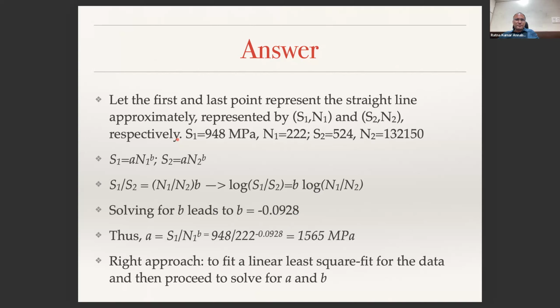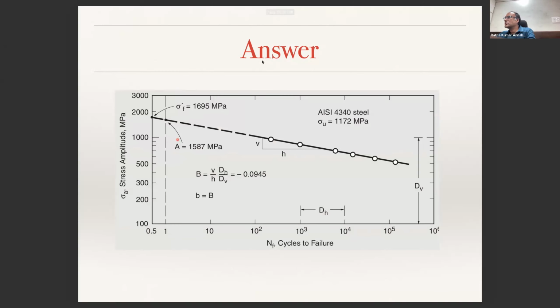Any questions there? If we take other points, we may get different results. Yeah, I agree with you. So the best thing is to do a straight linear least squares fit for the data that you have. That is how the stress life equation looks if you would plot it.